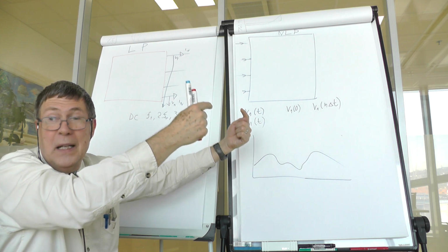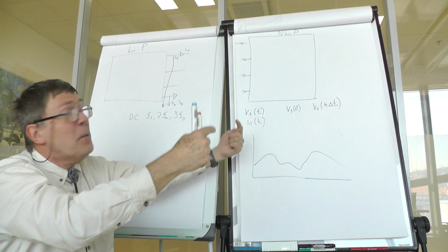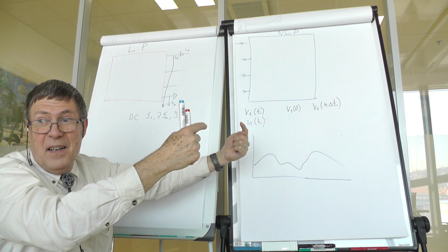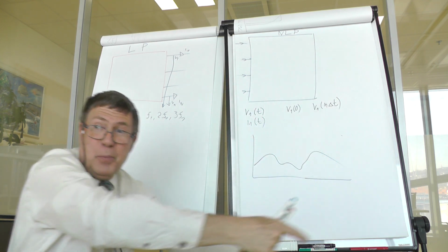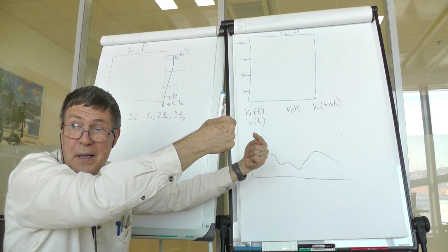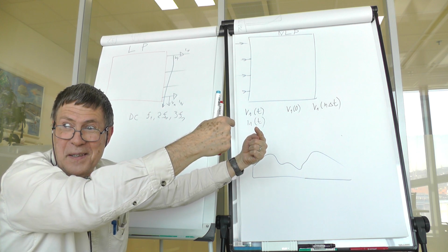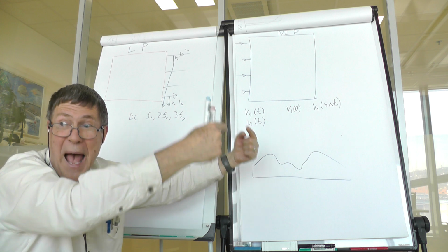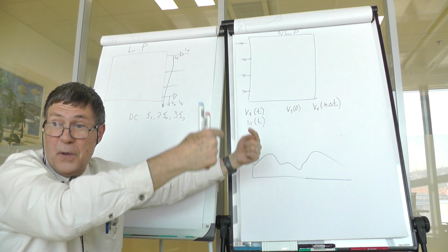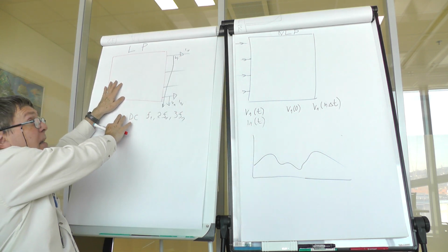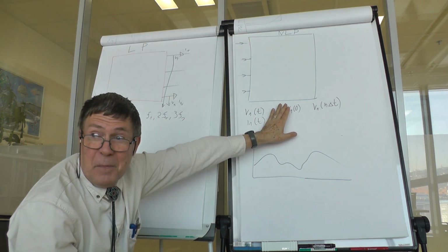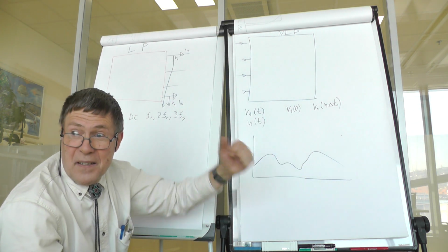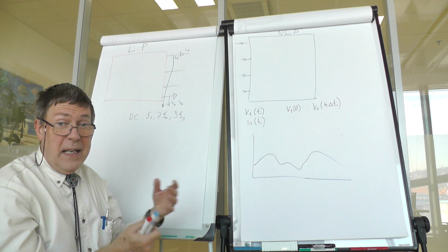We have to tweak the inputs as long as the outputs from this feedback loop are identical to the inputs. At that moment, we have harmonic balance. We have balanced both parts of the circuit, the linear part and the nonlinear part. And this is the method.